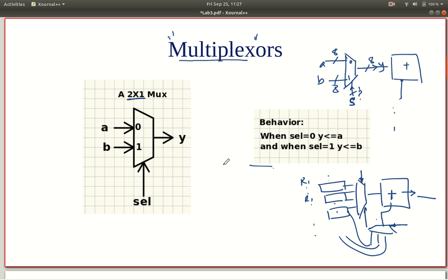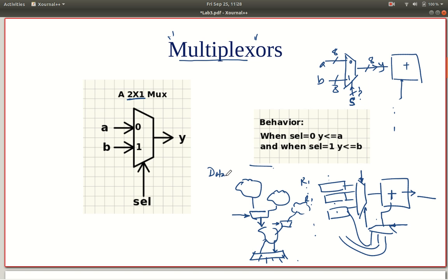So this kind of thinking, that you have some circuit, you have many sources, you have a mux, then you have some other circuit, you have another mux, another source. This could go to many other places, and so on. This is a demultiplexer and so on. It's like thinking like a traffic police. You're just directing where the data should flow from. Using these select lines, you're controlling the flow of data. So for this mux, you're controlling whether this is connected here or here and so on. This kind of thinking is called data flow style of thinking or modeling circuits.